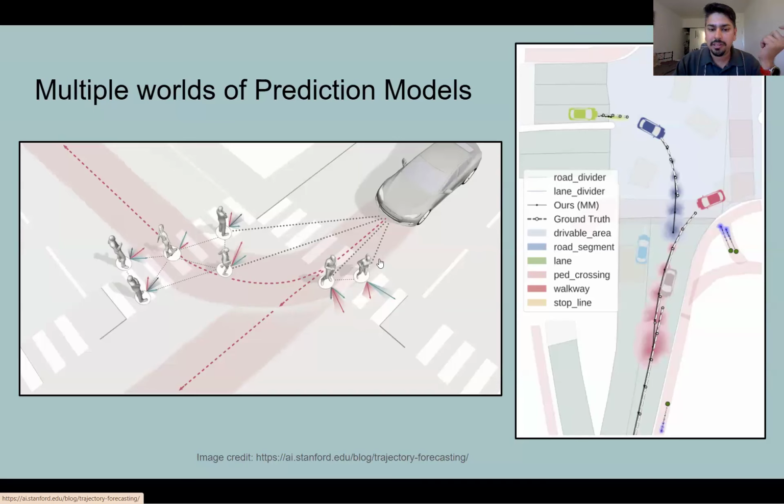One of the most prominent ones is multimodal predictions, which means that you have different modalities, and then for each modality, let's say the vehicle is going straight, left or right, a lane change or something like that, you have an assigned modal prediction, and the uncertainty maybe laterally, longitudinally, or time-wise. You have the uncertainty bounds of that prediction. That is kind of the industry standard, mostly a multimodal prediction.